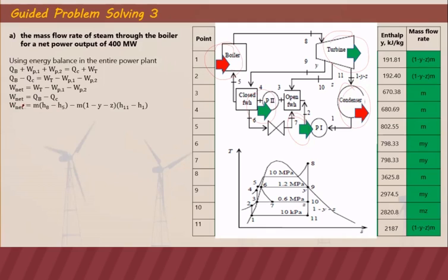So our heat input in the boiler is just equal to the mass flow rate at the boiler, that is m, multiplied by the enthalpy difference, H8 minus H5. For the condenser, the mass flow in the condenser is equal to 1 minus y minus z. You can see here at 1, 2, and 11. So that is 1 minus y minus z.